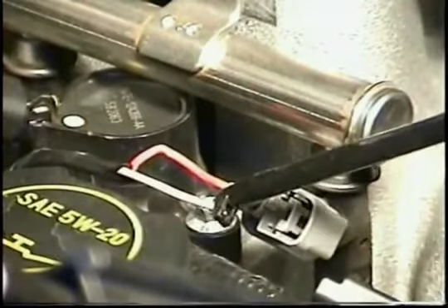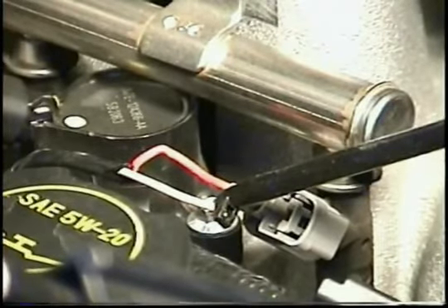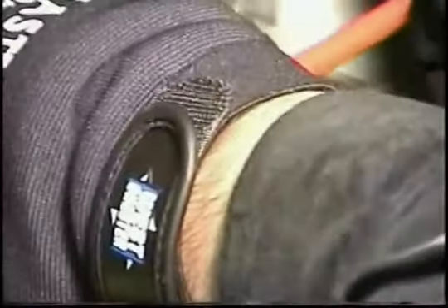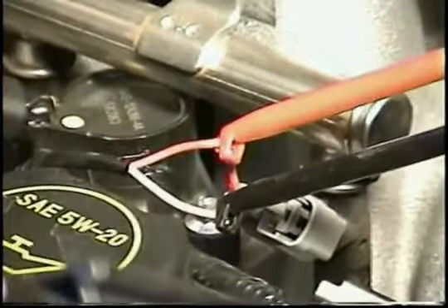This type of waveform yields a totally different type of information than the current ramping waveform seen before. We are using the Vantage graphing multimeter. And by using the waveform viewer part of the menu and connecting the black and red leads, we can immediately acquire and capture a voltage waveform from the injector wires.